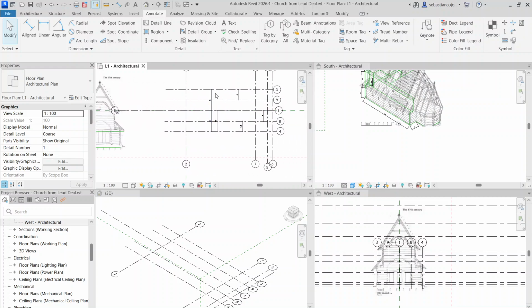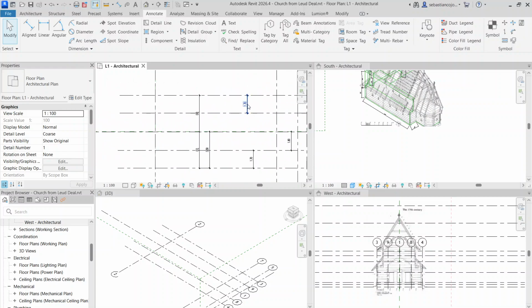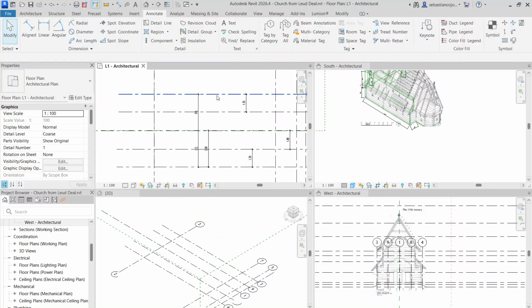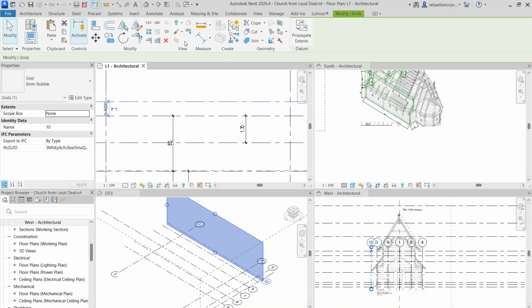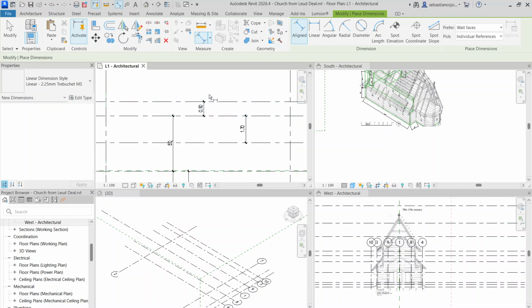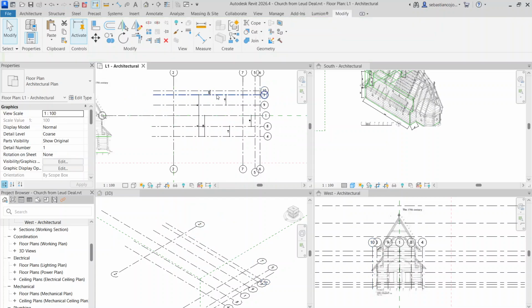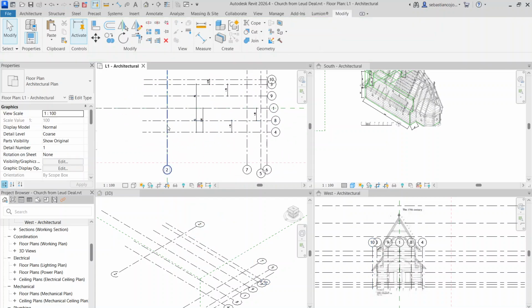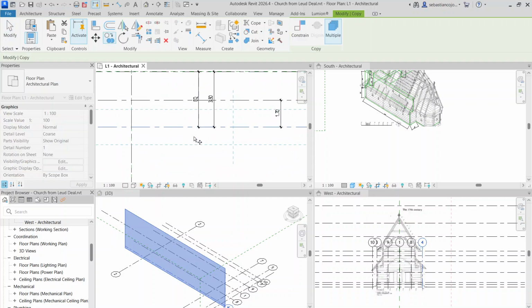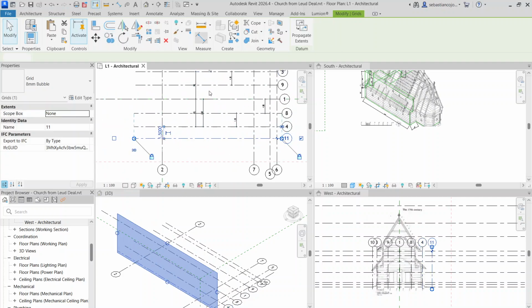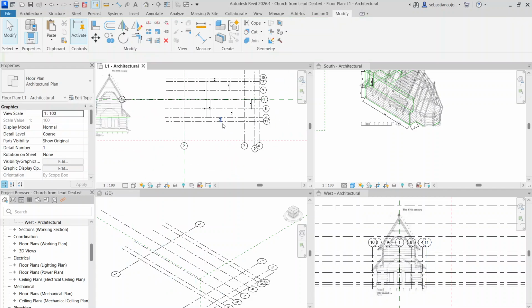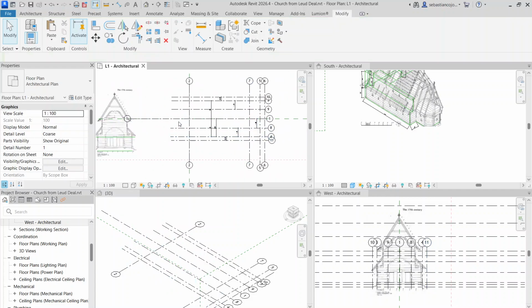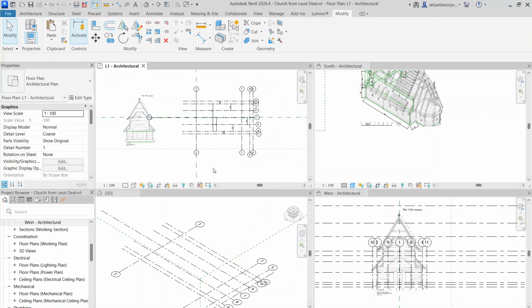Okay, so aside from this, this is the main building, let's say width. I will create another grid which is offset, let's say 0.7. That's an addition, 0.7. This is outside of the building footprint. Okay, let's draw another axis, 0.7. So this is outside the building's footprint. So yeah, I kind of have everything set up in place.